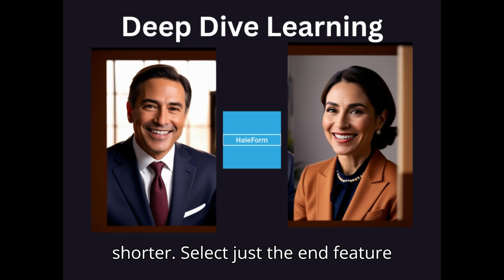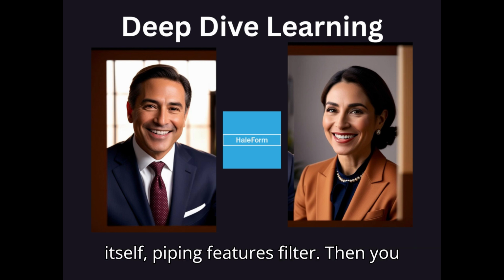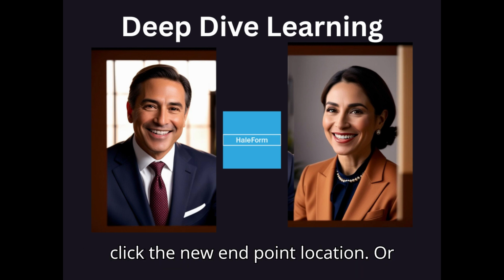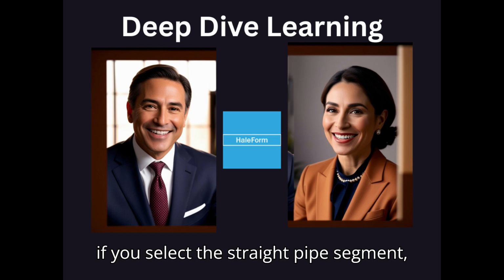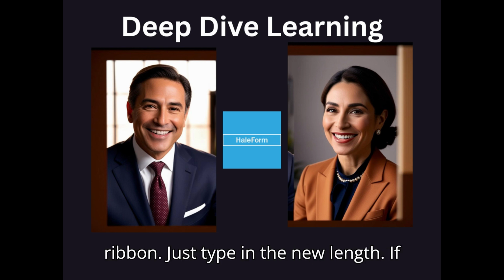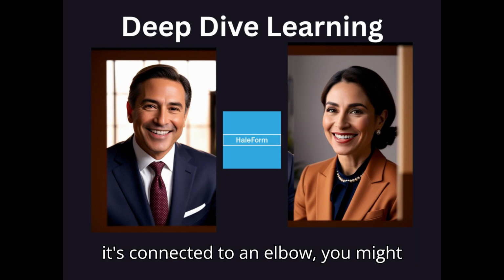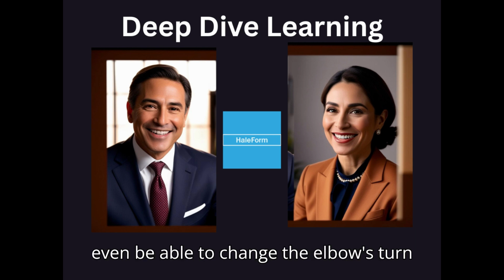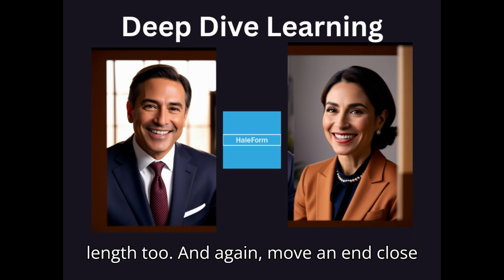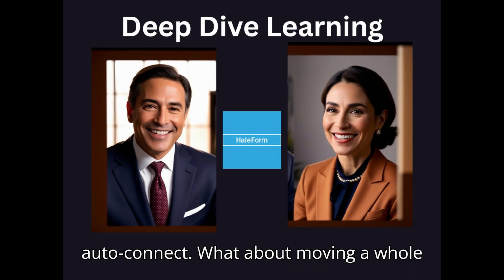And just making a pipe end longer or shorter? Select just the end feature itself, Piping Features filter. Then you can often use Move To from the ribbon and click the new endpoint location. Or if you select the straight pipe segment, there might be a length box on the ribbon. Just type in the new length. If it's connected to an elbow, you might even be able to change the elbow's turn angle, which changes the straight's length too. And again, move an end close to another open end, it may auto-connect.